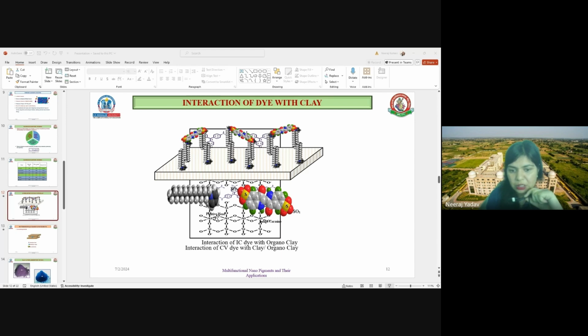So you can see here, through the solvent casting method, these polymer films which I obtained. The polymer films obtained in case of the organomontmorillonite are more transparent and more homogeneous because of the more homogeneous dispersion of these nanopigments. But in case of the pristine clay minerals, the particles can be easily seen by the naked eye, which is not possible in case of the organomontmorillonite.